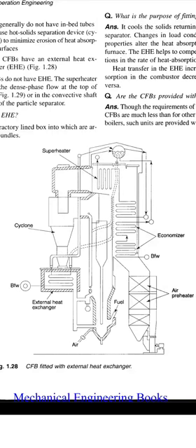The flue gas goes through the boiler from bottom to top, and the cyclone separates the unburned coal or some solid particles, which go back to the bed through the pipes, through the external heat exchanger also. The superheater is also available at the top of the boiler, and the flue gas goes to the economizer. Feed water inlet is given to the economizer, and it goes to the boiler drum. After that the steam goes to the superheater.